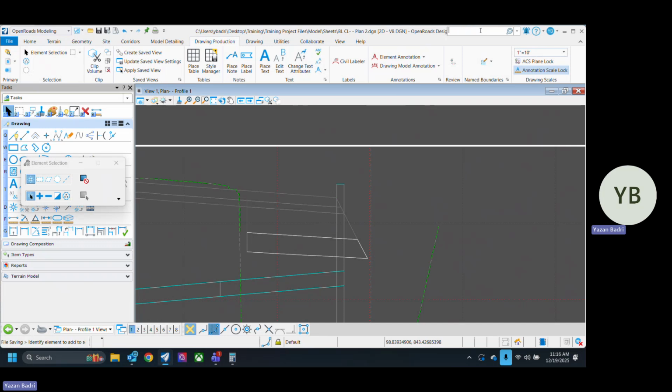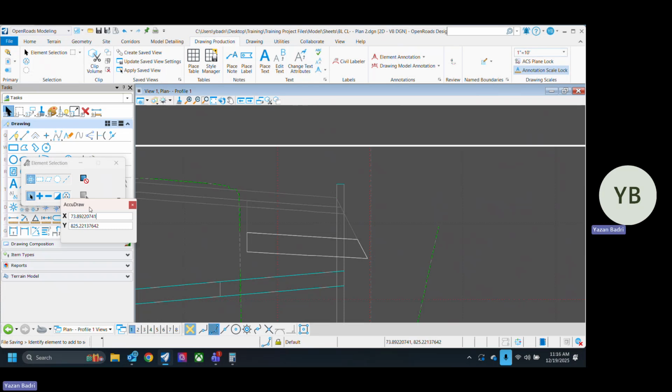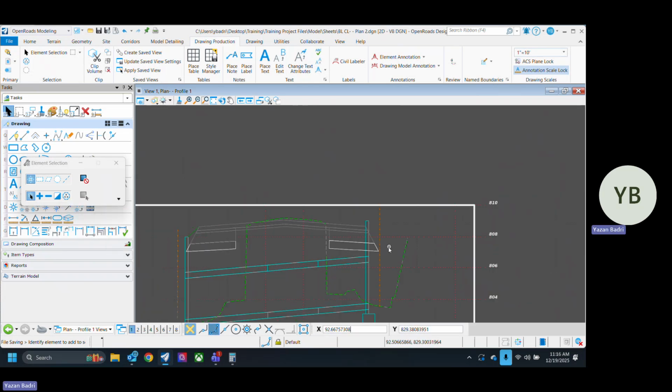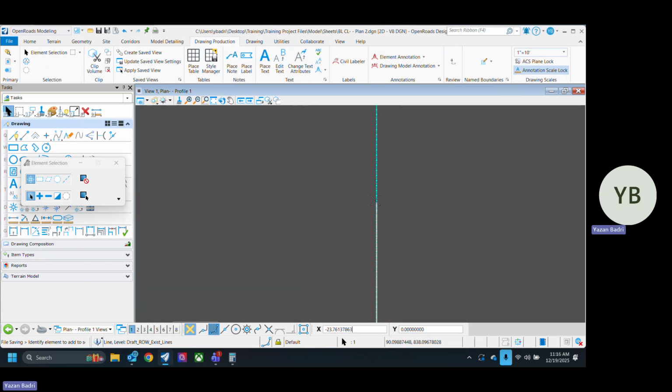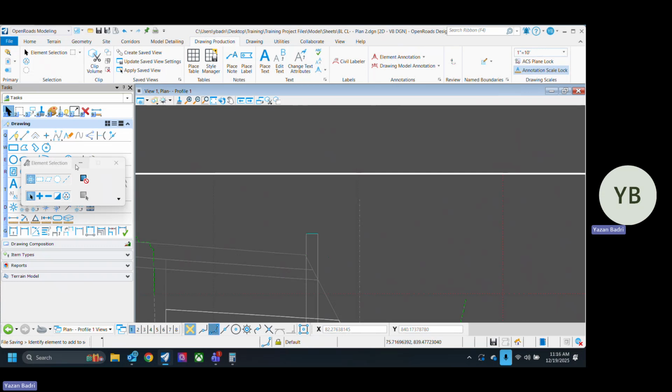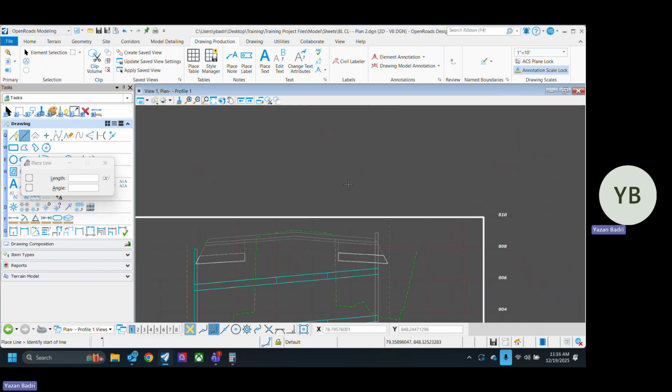Yeah. What is this called? Toggle AccuDraw, you know this one, right? I know it, but I don't know what it's for. Let's say I have this line and I want to keep it in the same plane or, you know, keep it vertical. See how it locks? There's a lock, it locks it for me. How's that different than using the on the line? You can do the extend also, it's the same thing.